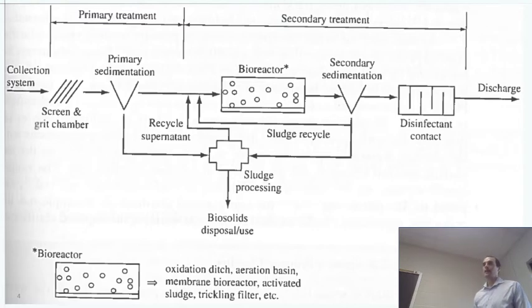That plus the first sedimentation will be what we call primary treatment. So for wastewater, we have primary, secondary, tertiary. And primary is essentially the very base physical stuff we can do, right? It should remove heavy particles, large objects, that kind of stuff. And in doing so, that will actually collect some of the oxygen-demanding substances. So if nothing else, this will be good, and I think it would be anywhere from 20 to, I don't think it's up to 50. It'd probably be like 20 to, and I'm kind of just guessing here because it's been a while since I've looked at the numbers. Maybe I have it in my slides later.